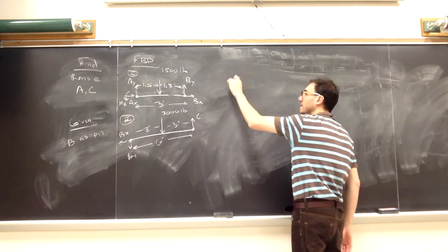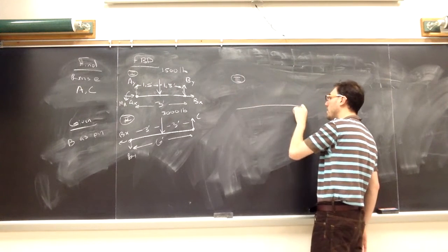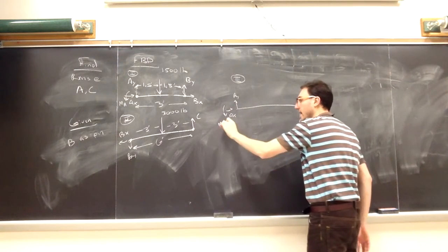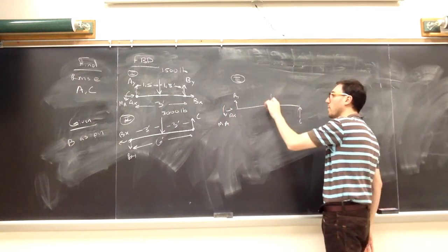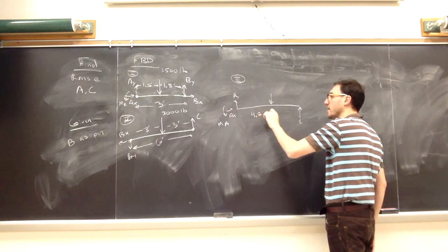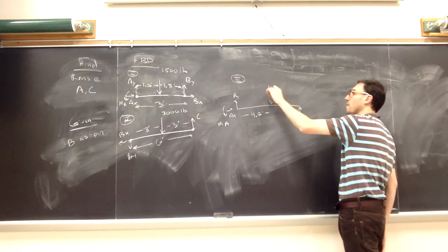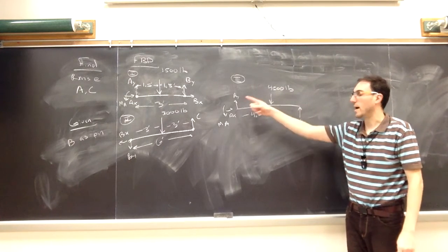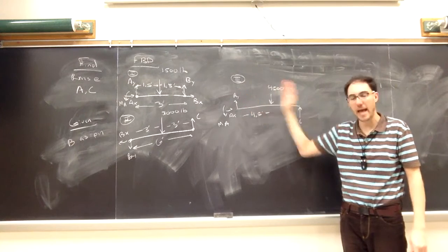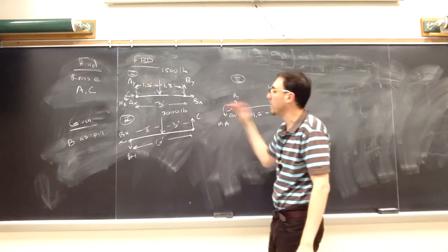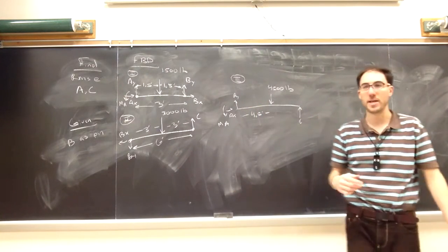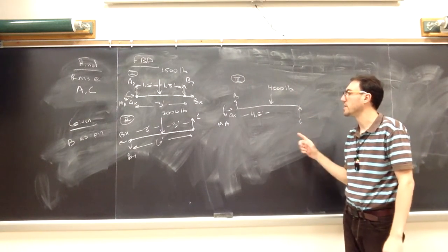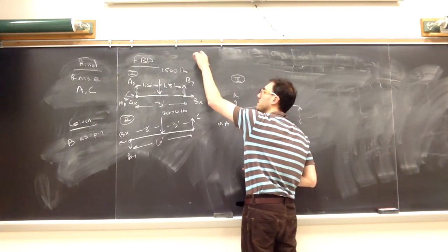As an aside, if I did decide to draw the external picture, which would be okay, then I would see the C, the AY, the AX, the MA, and here this sees the entire distributed load, so I would put at this halfway point, the 4.5 feet, that load of 9 times 500, or 4,500 pounds. And this would be an okay picture to draw because I'm including A to B and B to C, so that segment sees the entire distributed load on it. So these three are potential free body diagrams I could draw for this picture. But I'm going to just use 1 and 2, which are going to be enough to solve this. Any questions on the free body diagrams for this situation?